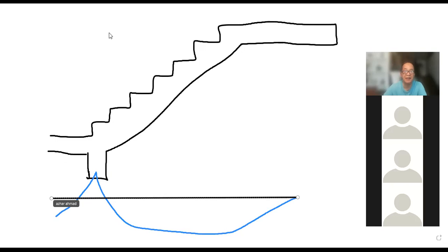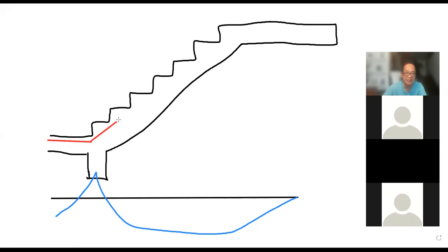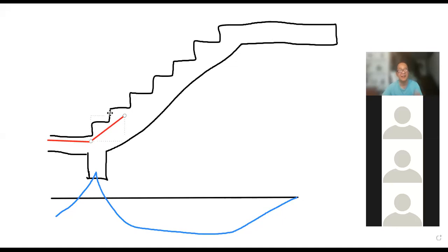So we have a negative bending moment, which means that kita punya reinforcement kena ada negative reinforcement to provide for a negative moment, which means theoretically we need reinforcement top side, sebelah atas, on one side sini, dan sebelah sini. Basically that is what it means. Itu yang dimaksudkan having negative reinforcement to resist the negative bending moment pada penyokong. Between support sini dengan hujung sini is to have our bottom steel. The understanding is bottom steel.